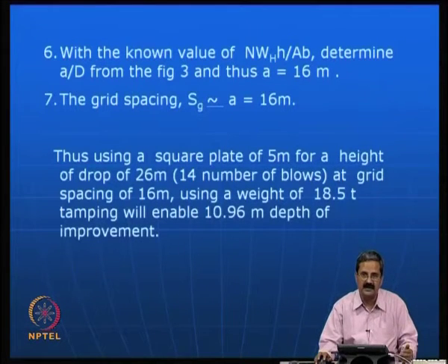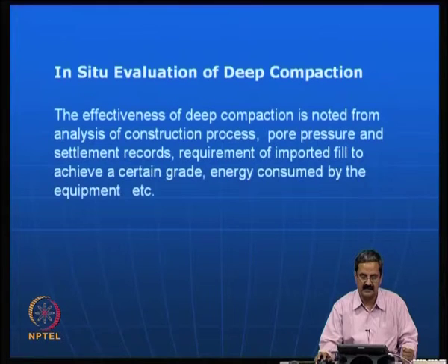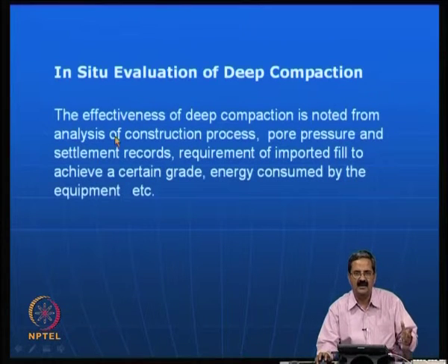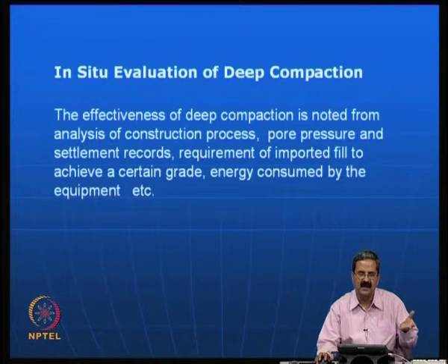So, one can check and then come out with a simple design. As I just mentioned, the design is very simplistic, and the best thing is that you have to verify to what extent this deep compaction is effective. So, what you do is go for in situ evaluation of the deep compaction methods, and the way we do it is to analyze the construction process itself, how the process is designed. Using the calculation procedures we have seen, we can do a parametric study and arrive at a proper construction sequence.